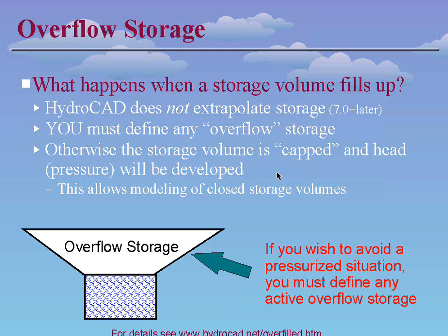So in general, the key is to define your storage to some distance above your highest outlet device. You will get a warning message from the software when you do the routing if your storage does not go high enough. So you'll want to check that message and make sure that you define that additional storage. When you do this, you're not setting up fake storage. This is very real storage that you're providing. And so it's going to be the actual volume of water that is occupied by the water at any given elevation.